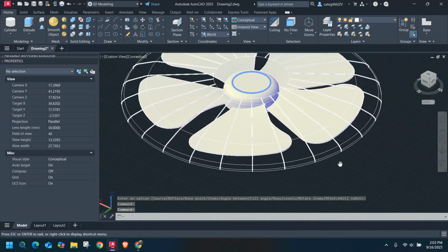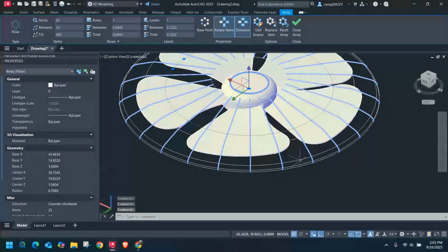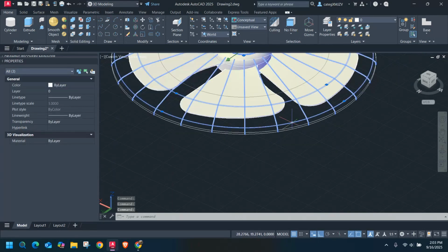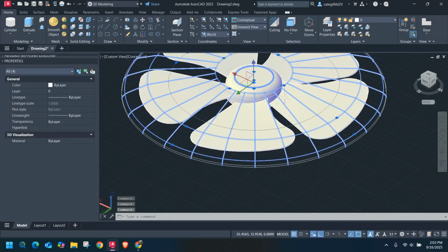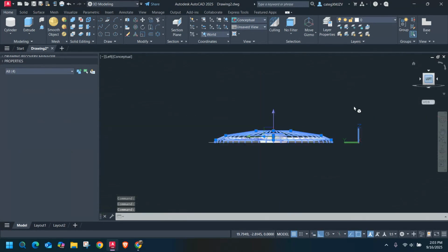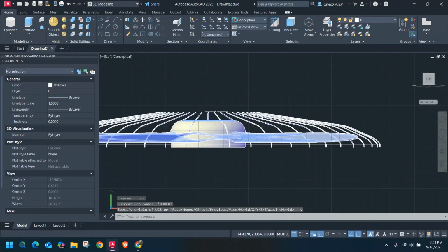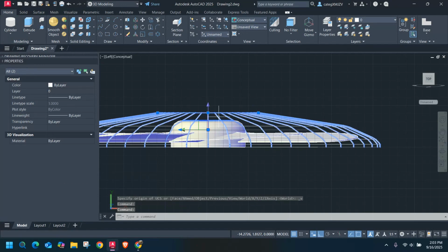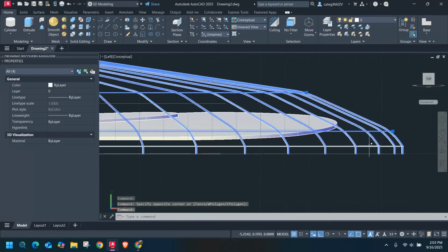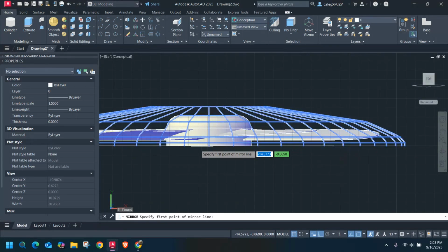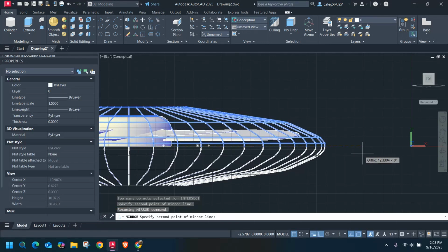Now, what you can do at this stage, and you're gonna need at least like, you're probably gonna need all of these lines to mirror too. Okay. You're gonna need your polar array, your line here, your line here. You can see them, right? To mirror. And then pick your midpoint and just mirror them.